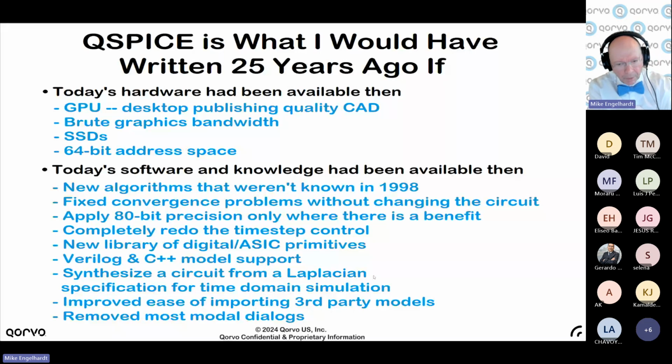And that gives you the impulse response, because you know that the Fourier transform of a delta function is a flat line in frequency, all frequencies equally considered. So if you take the way your behavioral part colors that flat response and do the FFT, you get what comes out from an impulse response. And then you convolve that impulse response with the actual waveform in the time domain that you apply to the input of your transfer function. So, that's a simple idea. What could possibly go wrong?